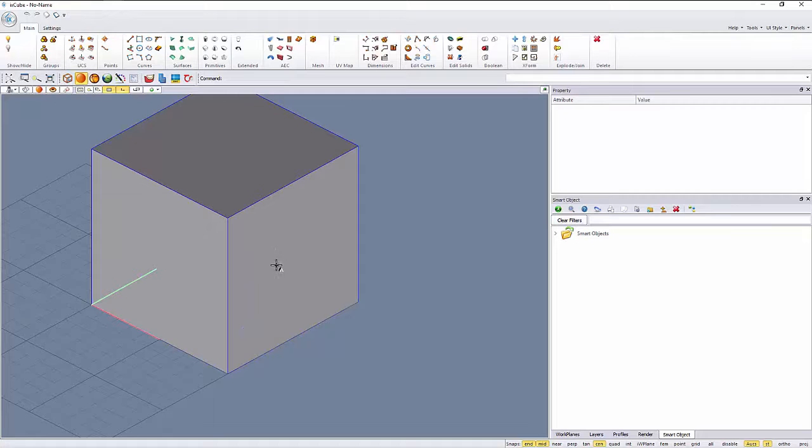I would like to underline, you see that near the cursor you see an A. Auto UCS is active. That means basically when I try to draw a curve like this, the software detects the surface on which I am going to draw. And be careful that if you draw something, the curve will be merged on the surface.